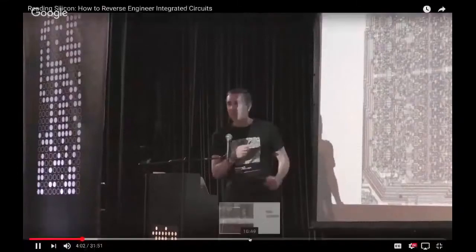Another thing is the Z80 has a couple instructions that will swap the data in registers. And it turns out that it's actually not moving the data between registers. Instead, it swaps the control lines at the top. So it's much faster than actually moving data between registers. So just one of these optimizations that you find inside a chip.